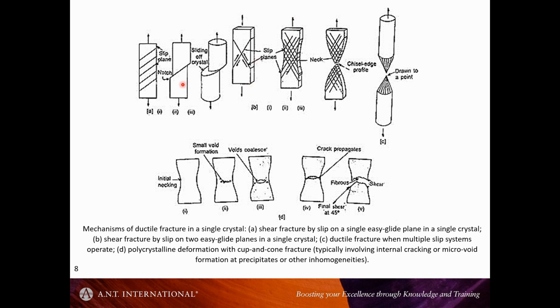So in this particular instance, the thinning comes about purely by shear, and it's ultimately purely ductile failure until eventually the material gets so thin that it can't maintain, and the atoms simply part at that point.